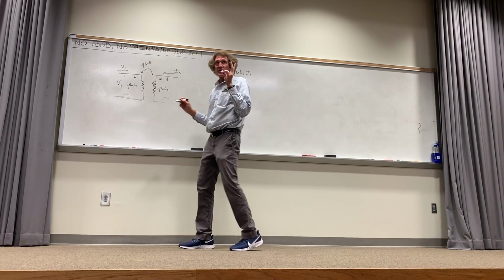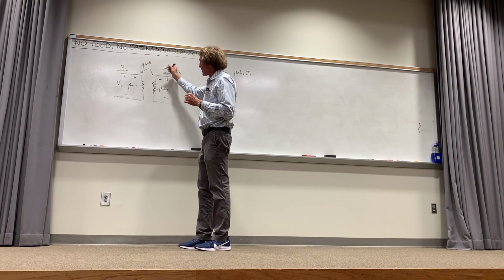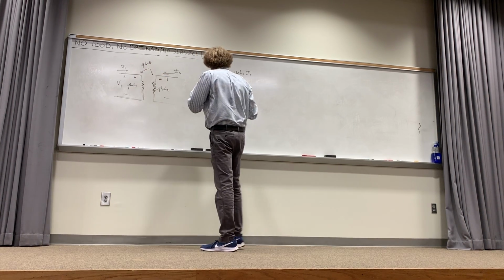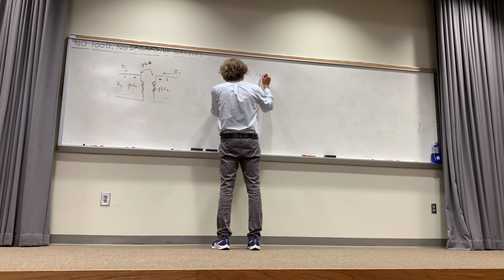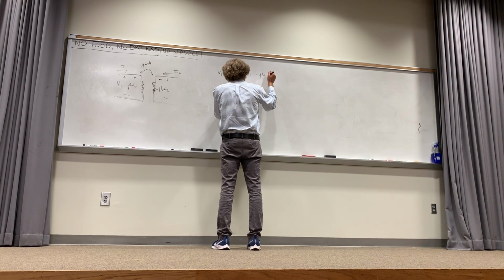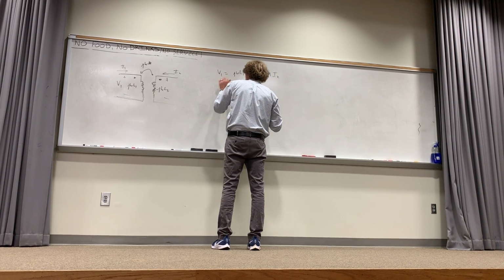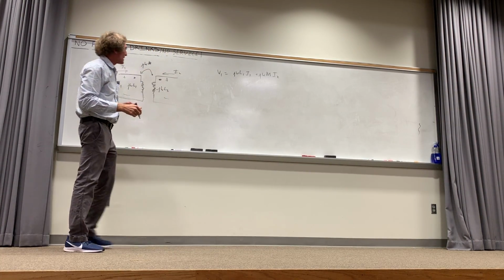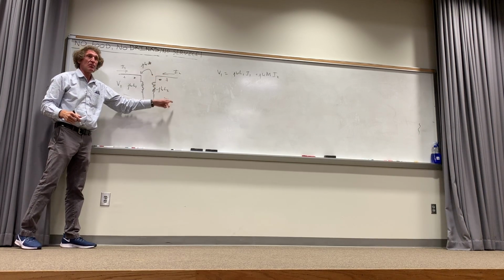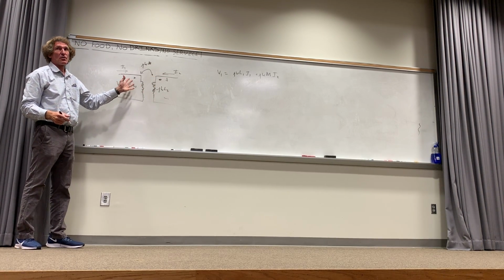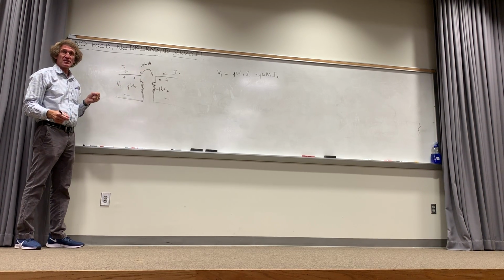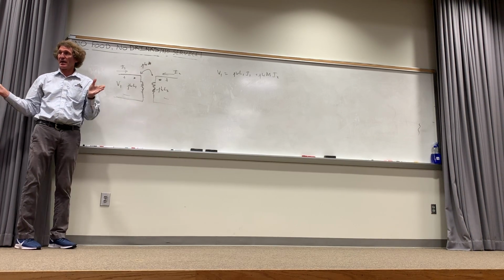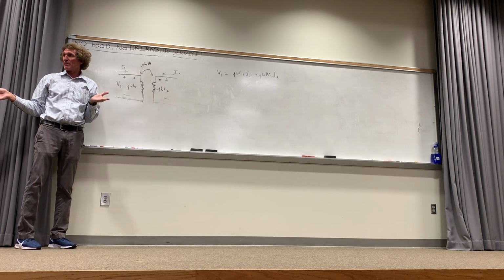But then there's a secondary effect where this current creates a magnetic flux that couples in there. The way we write it is, it's also going to have an impedance J omega M. I'm going to use M for mutual. You could put L sub M, but it makes more sense here. M times I2. So that's what V1 is. This current I2 has an effect on V1. As a matter of fact, if there was no current in I2, if there was no load, then the voltage on the primary side would just be J omega L times simply I1. Do you all see that, class? Because I2 would be 0. If I2 is 0, it's just like an inductor on the primary.